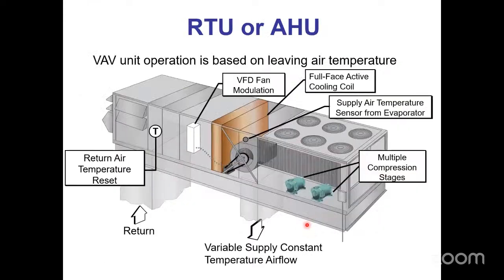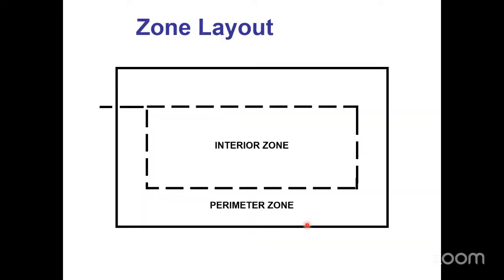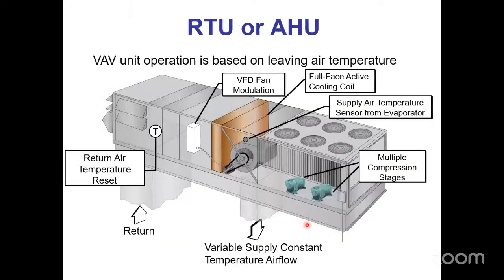All right, there are some things that are going to be requirements of our air handler. So specifically, a VAV air handler has two very major things different compared to a constant volume air handler or rooftop. One, I already mentioned, is a VFD. I need to have a way to slow the fan down. Now, I can have a VFD on a regular, quote-unquote, constant volume system nowadays. Typically, that is called SAV, staged air volume, and it's a two-stage fan. It goes to one speed when I'm in cooling 1 and a higher speed when I'm in cooling 2.